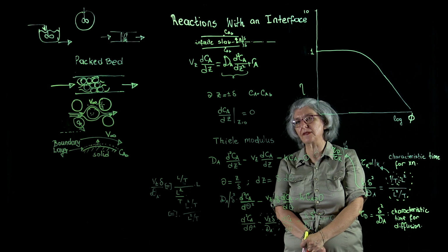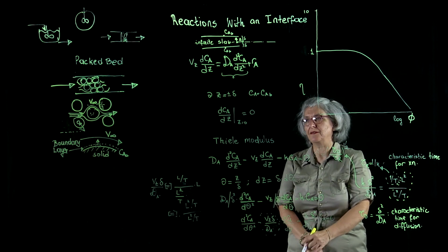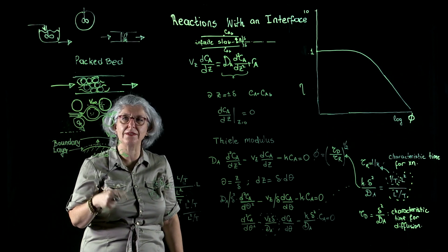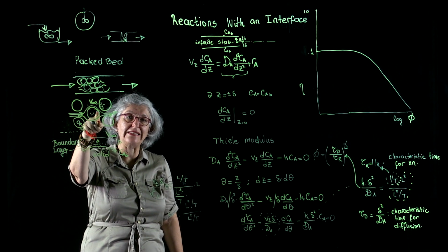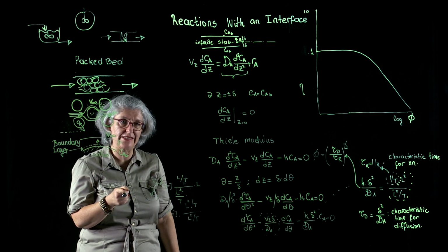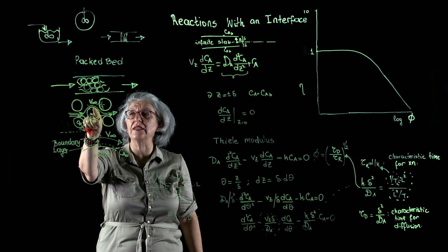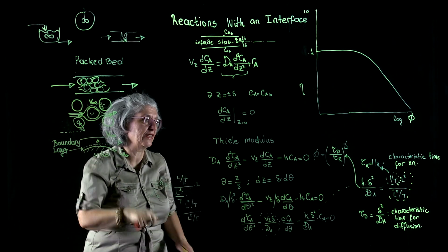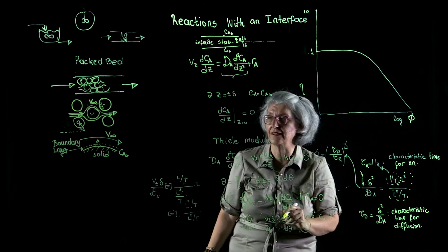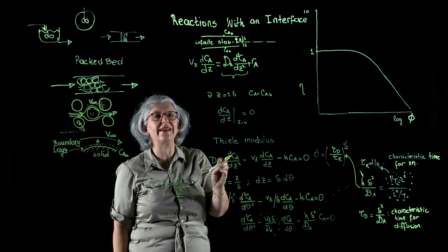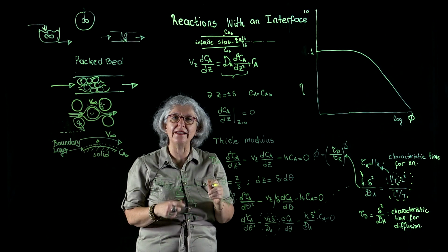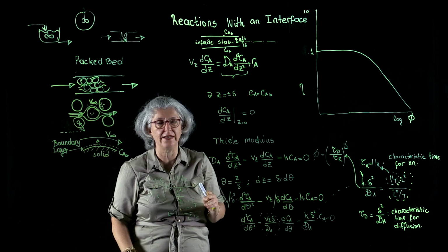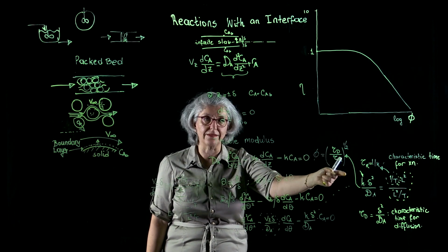Now what happens if we increase the temperature? Or if we change the temperature? Remember that in these reactors, endothermic or exothermic reactions are taking place. In other words, as a result of reaction, there is a heat generated or absorbed from the environment. And we are more concerned about heat generation. I will tell you why in a moment. Because heat generation is going to cause a change in the surface temperature, catalyst surface temperature. If the catalyst surface temperature changes, the temperature dependency of the rate constant is going to start to play a role in how fast the reaction is moving. So if we cannot remove the heat as fast as it is generated in such systems, and if our reaction is very rapid, we cannot do that very effectively, then our rate constant increases.